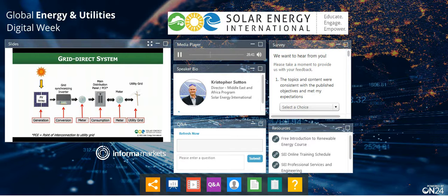So that becomes specific to the utility company or government or municipality or whoever oversees the electrical distribution company. So there's going to be what we call an interconnection agreement, some sort of a way that we agree on the price and the value of that energy that comes out of the solar and into the electrical grid. A lot of places still around the world will not allow interconnection to the grid, so we have a few other ways that we handle that, and we'll talk about that later in this lesson.